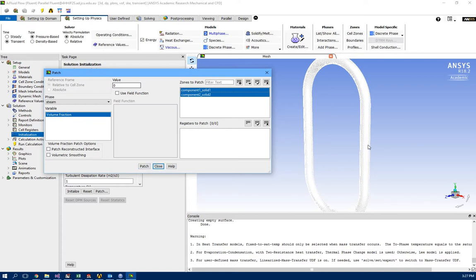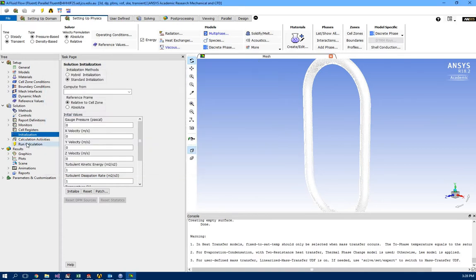Basically, the upper part is going to be air, and the lower part water, with no temperature. Then the temperature, the hot surface here is going to start, and water is going to start boiling, steam is going to rise, and when it goes up, the cold surface is going to condense the steam, and it is going to go back, and this heat transfer mechanism is going to continue.